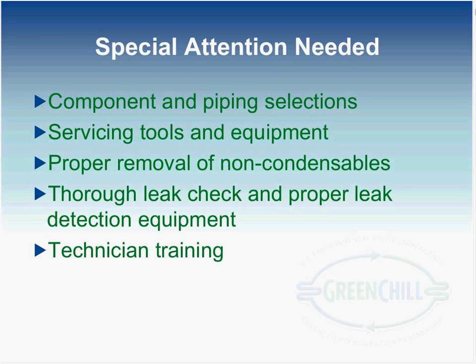Remember the chart that I showed earlier, with the pressures. At 90 degrees Fahrenheit, the pressure was over 1,000 pounds. In most service applications, the ambient can be anywhere from 75 degrees in the store to well over 100 degrees outside. So if a service technician were to use a set of gauges that had low loss fittings and do service on a CO2 system, once the temperature of the CO2 rose up to ambient conditions, the service technician would lose the set of gauges rather quickly.